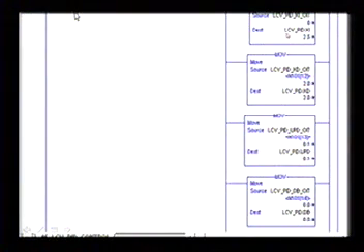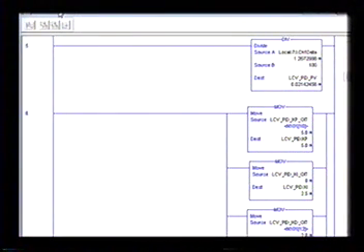And then here's your KI, your KD, your loop update time, your deadband, right? What you're doing is allowing the operator to adjust these values so that they can tune their loop. And why you want to do this is because if you've got this on your factory floor, you don't have what they have. You don't have the same values, the same process, right? Things change. So you want to give them the ability to tune these loops.